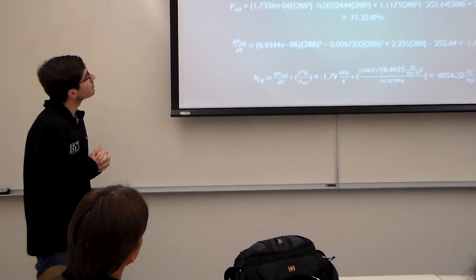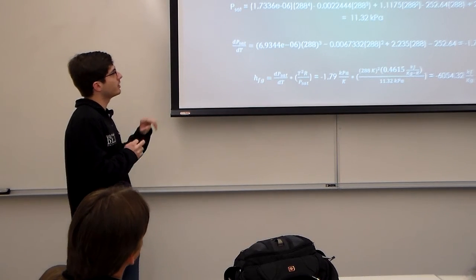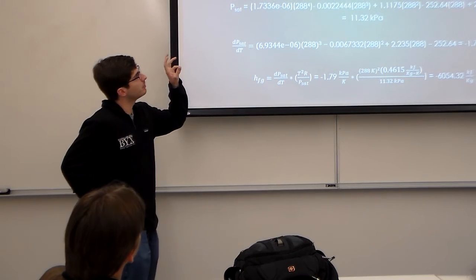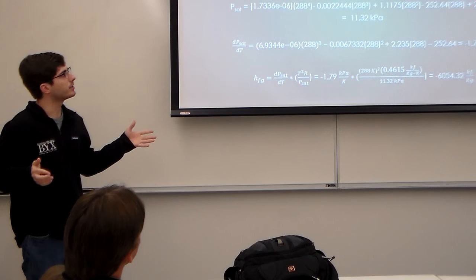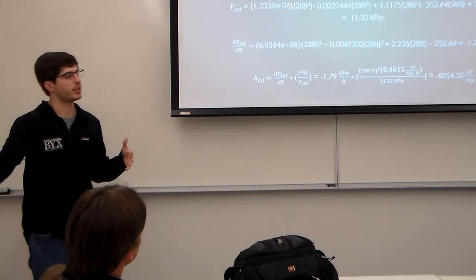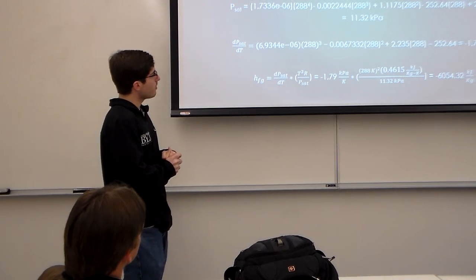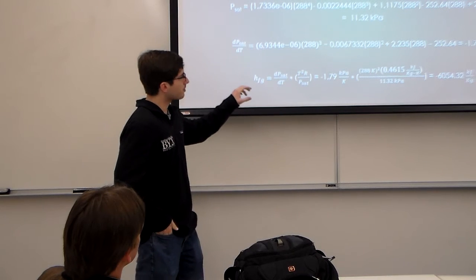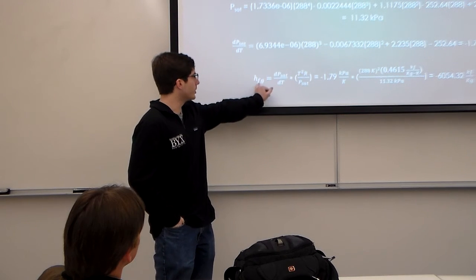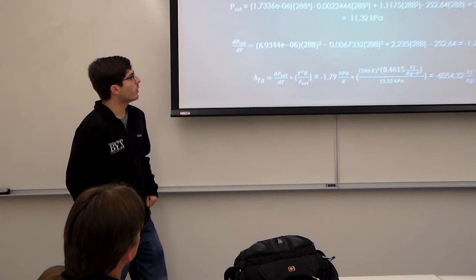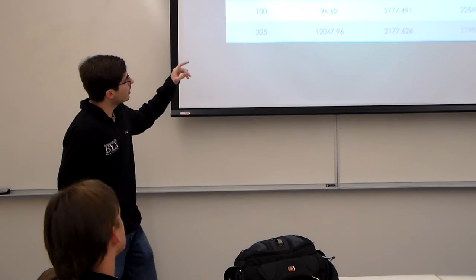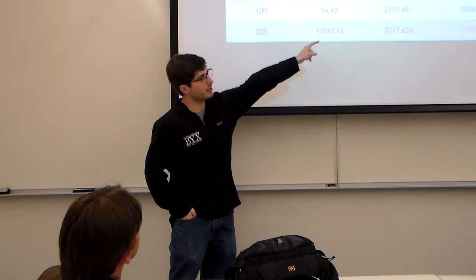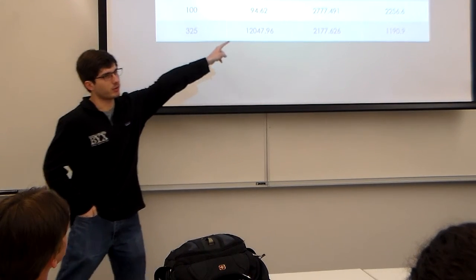Next. For the sample calculations, we took that PVT relationship, plotted the best curve fit, and then took the derivative of that to find our slope, because we need that to calculate our latent heat of vaporization. And then, rearranging the equations, you can find your enthalpy value, where for this example, if you go to the next slide, at 15 degrees Celsius, it says negative 6,000 for that equation.